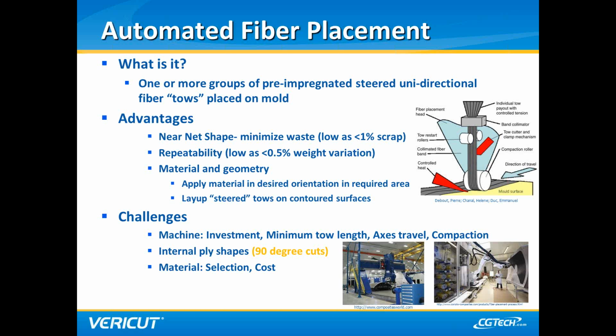Another advantage is repeatability. So when we talk about repeatability, really looking at weight variation. So because you're laying this up in a controlled manner with the similar program on a similar tool, seeing weight variations as little as 0.5% after cure and after trim.